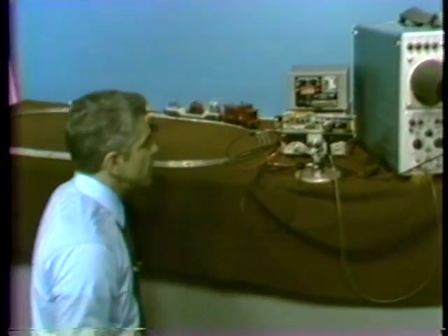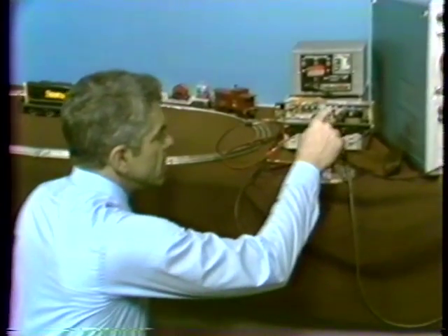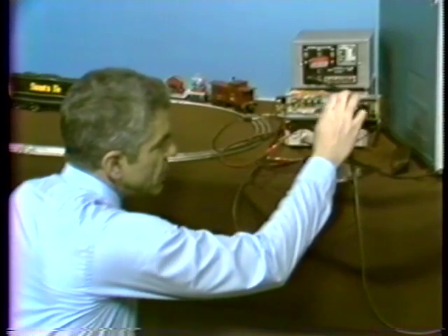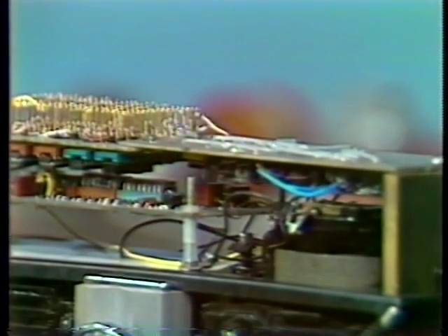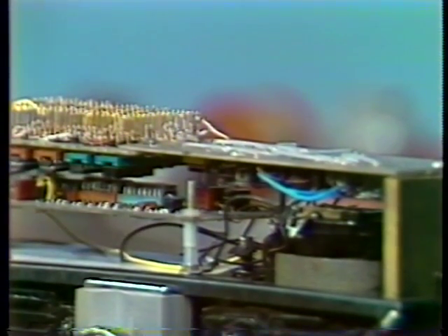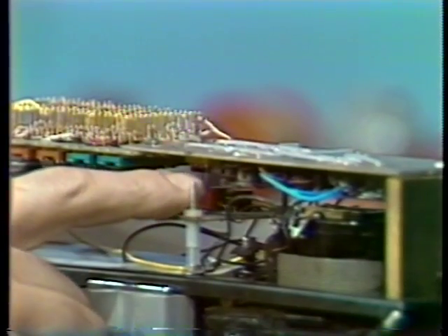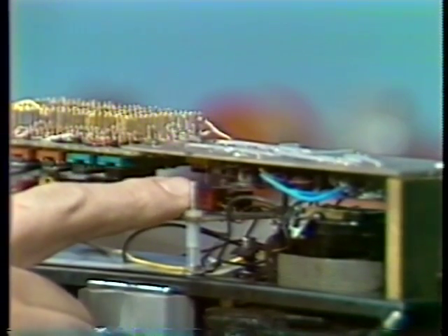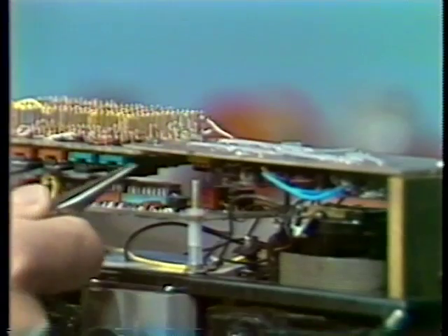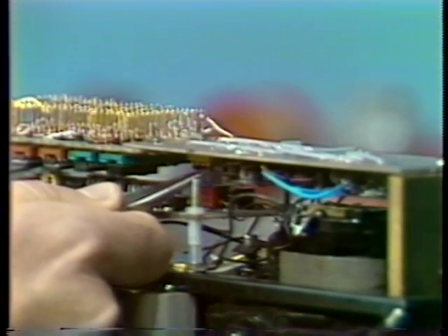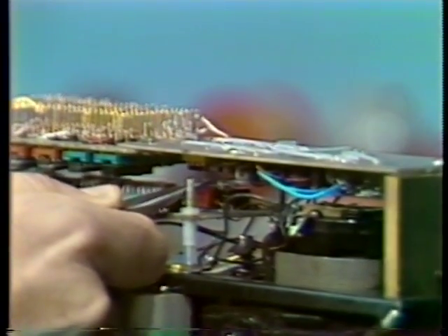The compensation is actually buried down inside the power amplifier. As I mentioned earlier, the power amplifier for the motor is in this portion of the configuration, and buried right in here is a little capacitor, an electrolytic capacitor actually, which is the thing that's doing the compensation. And let me pull that out.